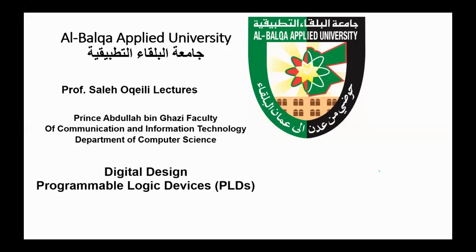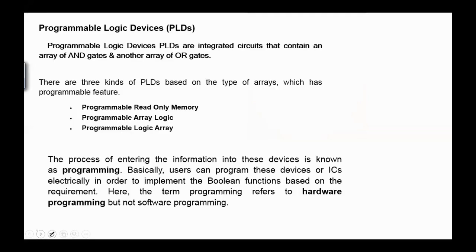Welcome again. Today we start our next topic on digital design course, Programmable Logic Devices, PLDs. Programmable logic devices are integrated circuits that contain an array of AND gates and another array of OR gates. There are three kinds of PLDs based on the type of arrays, which has programmable feature.